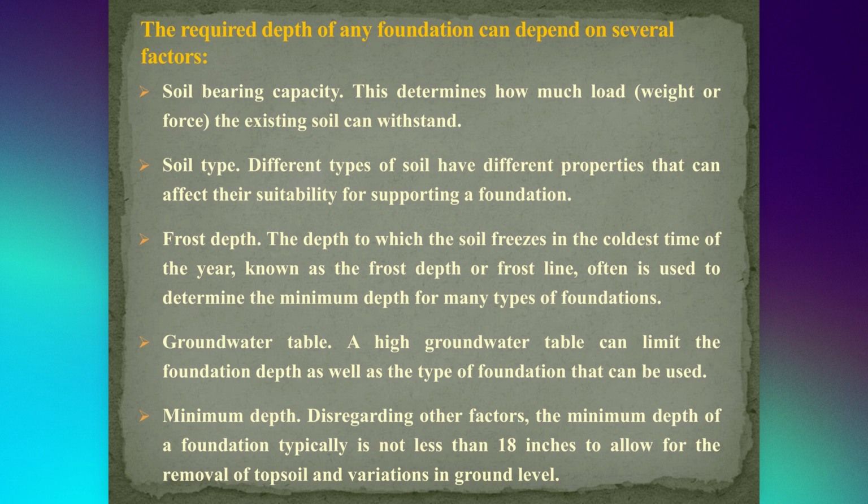Groundwater table. A high groundwater table can limit the foundation depth as well as the type of foundation that can be used. Minimum depth. Disregarding other factors, the minimum depth of a foundation typically is not less than 18 inches to allow for the removal of topsoil and variations in ground level.